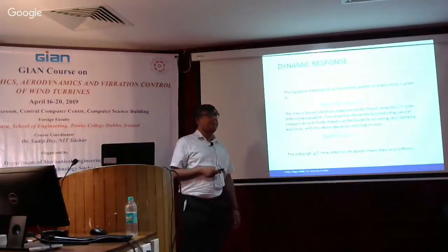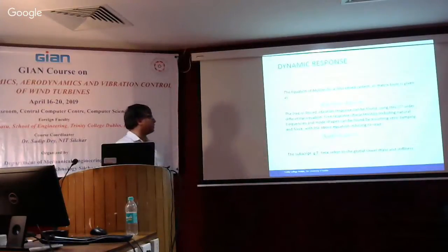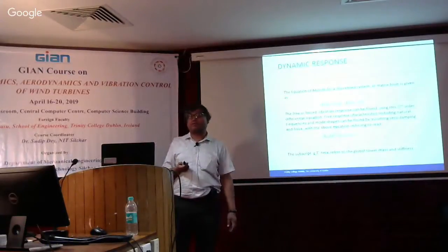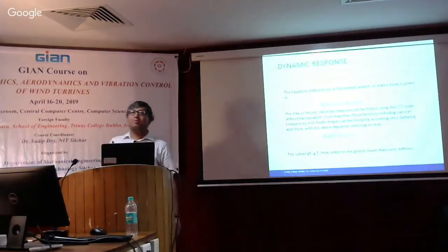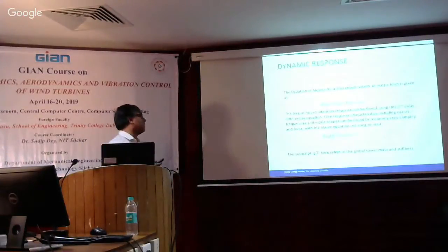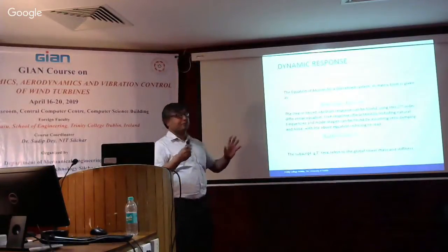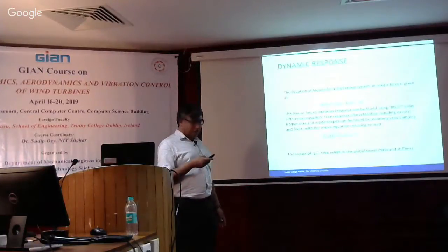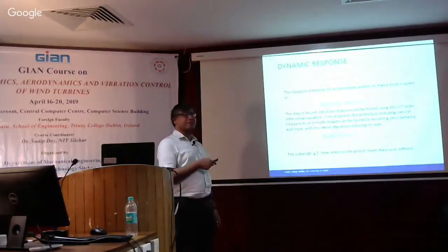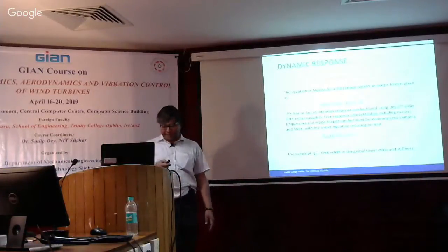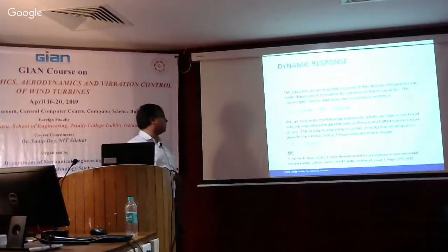And for the dynamics problem, as I said, you also have to consider the inertia and appropriately consider the mass matrix. There are various ways you can have the mass matrix: you can have the lump mass matrix, you can also have a consistent mass matrix, or you can derive the mass matrix based on some continuum approximations as well. Once you have the stiffness matrix and the mass matrix, either lump mass or consistent mass matrix, then to solve for the mode shapes, we usually ignore the damping part and proceed to solve this equation, and then eventually we can get the natural frequency and mode shapes.